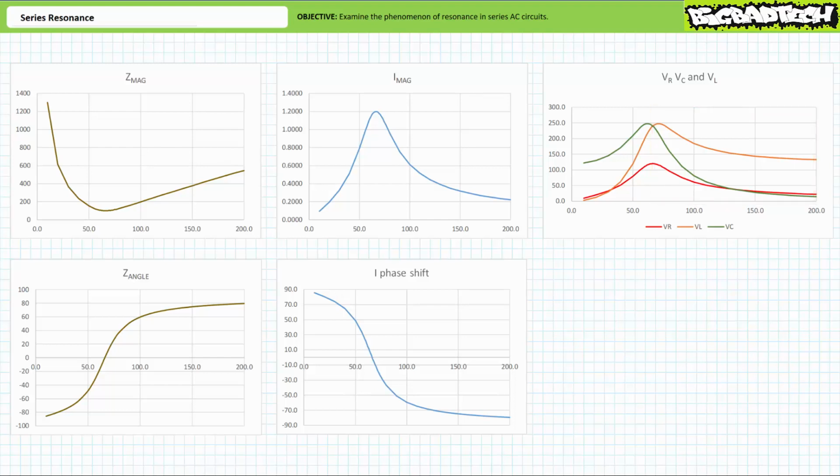What's especially satisfying about these general purpose plots is that if you understand these general purpose plots on every level that I'm asking you to do, you by extension understand fundamental behavior for all series resonant circuits. Long story short, all series resonant circuits experience peak current magnitude at the resonant frequency. If you don't hit the target, the magic will not happen.